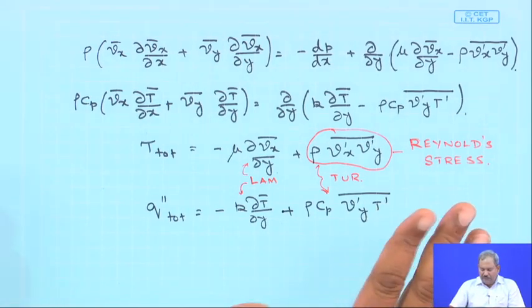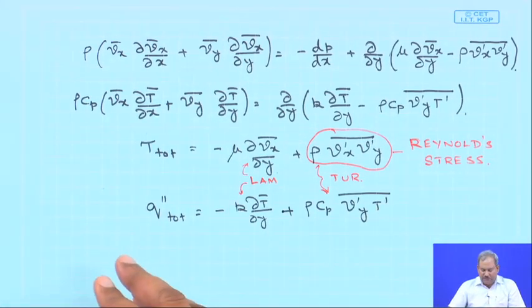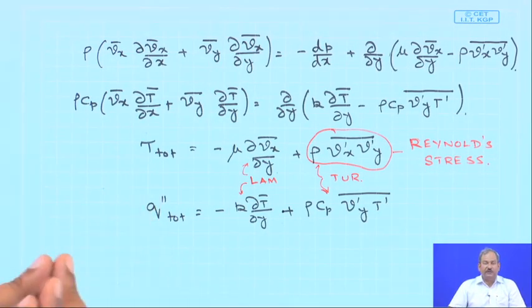Now, when it is expressed in this way, sometimes it is more convenient to express it in terms of something which we use very commonly, we call it eddies. So, what are eddies? You can conceptually say that eddies are nothing but packets of fluid which has a very short length before which it disintegrates and mixes with the fluid stream once again.